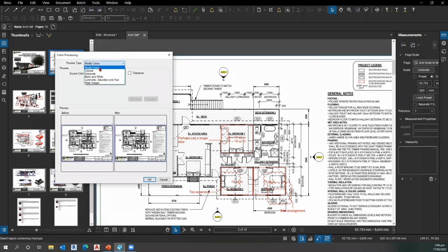And there's one option called Modify Colors. If you have a host of other, like greens and purples flying out everywhere, you can just choose the grayscale option if you wanted to as well. Okay, if you choose this, it will just turn whatever that's black into gray or white. Okay, but we're going to choose Modify Colors. And I'm going to go Source Color, black, to, let's say, very light shade of gray.